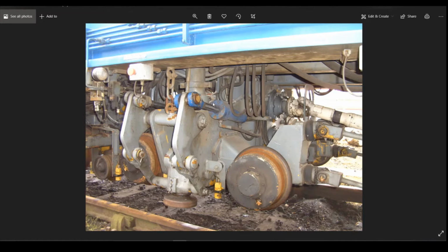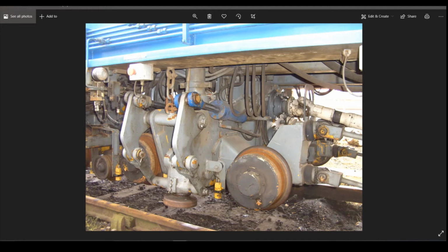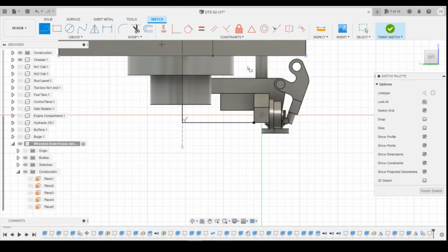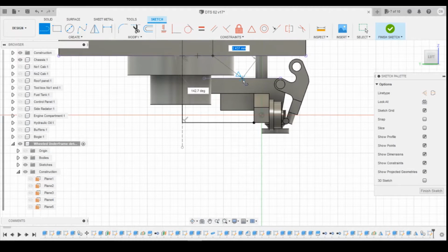Now the top half, it looks like it's in line roughly where the pin is, and comes up a little diagonal and then up and across. So if we just draw a line across maybe 2 millimeters, like that. So we know this pin is here, and that's this one that we're looking at here. So we can draw a line that comes from this top line. Again, we're going to have to project that line, and then we can draw from there down at an angle. I'm going to, maybe the halfway point on it. I'm going to use that. That's going to work for me.